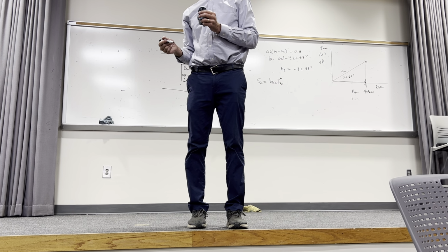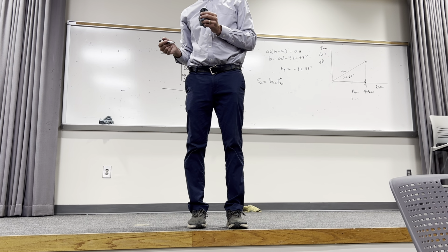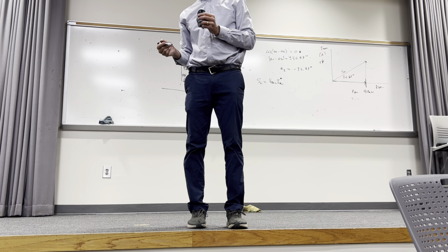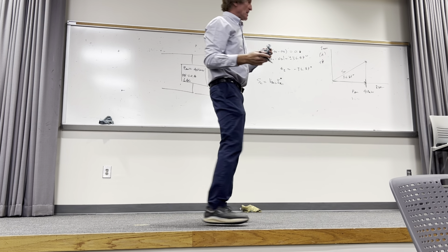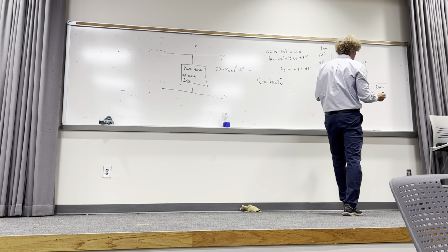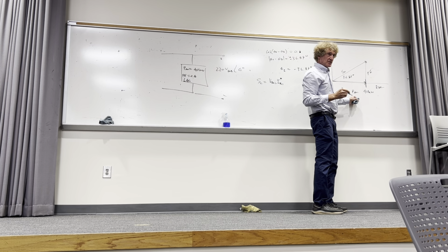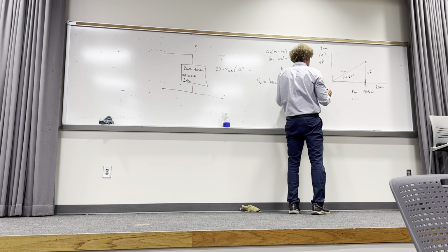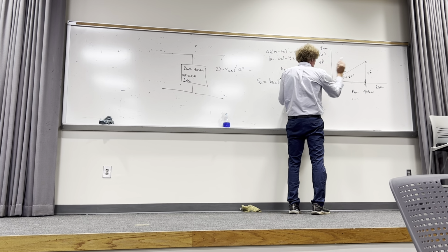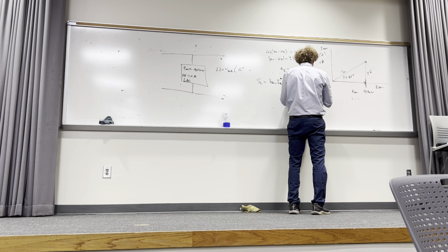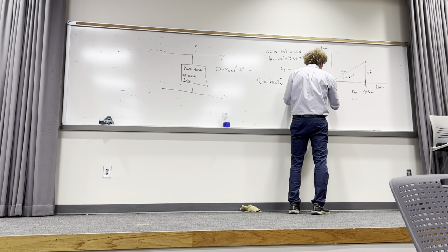Whenever I see a right triangle and I got one side, I'm either thinking cosines or sines or tangents. In this case, how about we use tangent, right? If you look at this, this is what I want, the jQ, right? I've got this at 40 kW. Do you agree with this? So if I take a look at this, I have Q, the opposite over the adjacent, or 40K, would be equal to the tangent of 36.87 degrees.